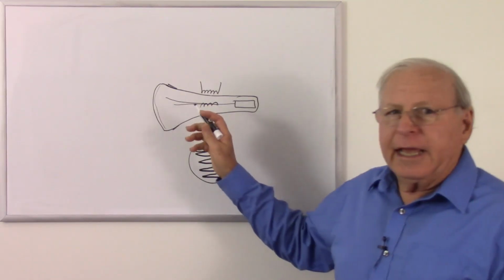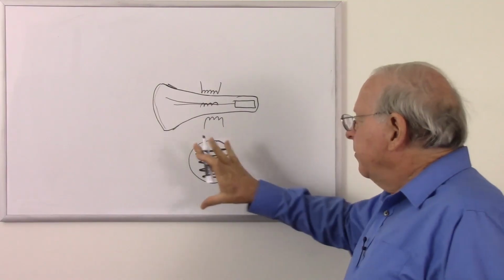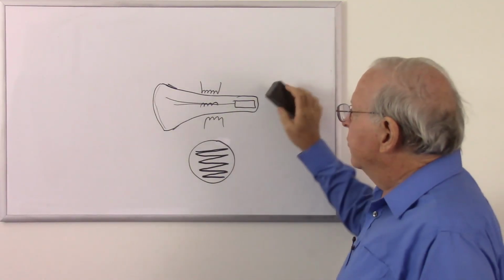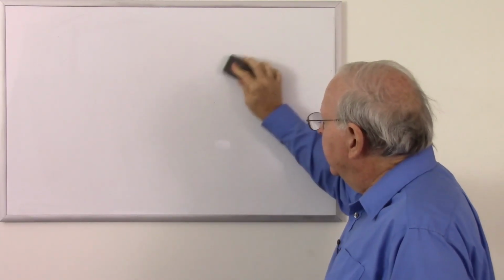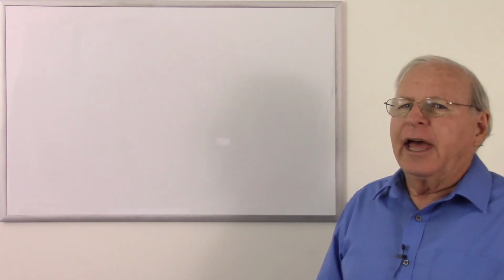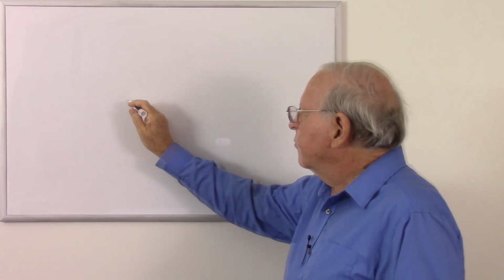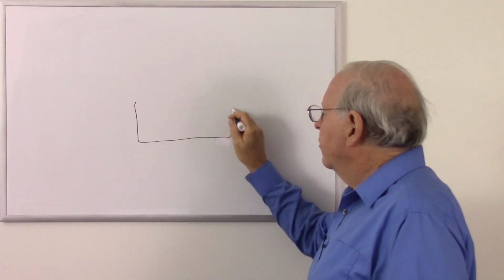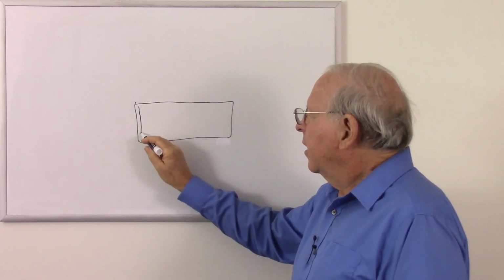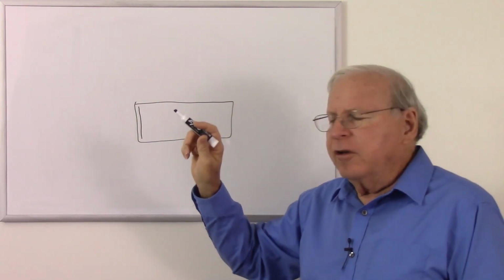But let's move to the beginning and look at creating some kind of a camera that could create something that could be sent to this CRT to create that image. And Farnsworth is credited with developing the first working camera tube, and that was called the image dissector. So basically what he had was a cathode ray tube that sort of worked in reverse. So here's the front of it, and it's kind of a squarish tube if the diagrams I've seen are correct. And he had a screen here of material. I don't know exactly what it was, except it was coated with cesium oxide.